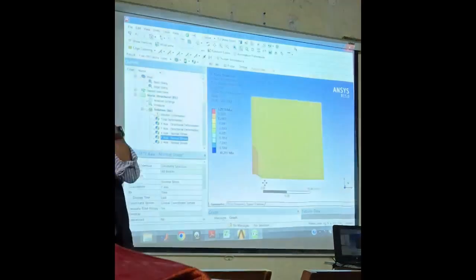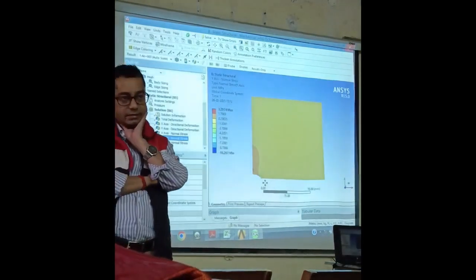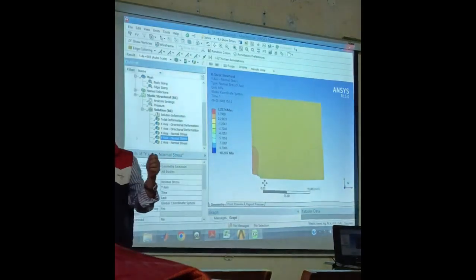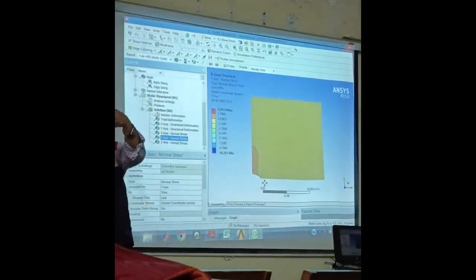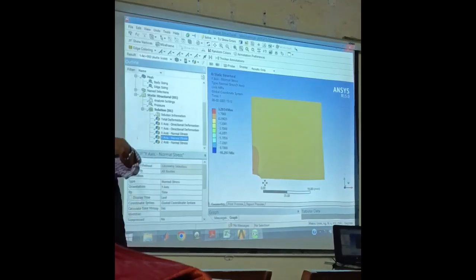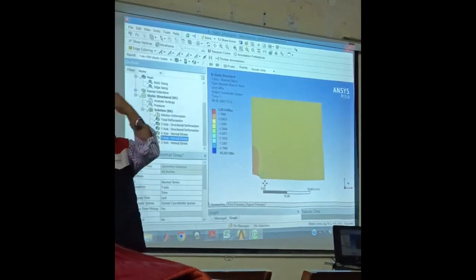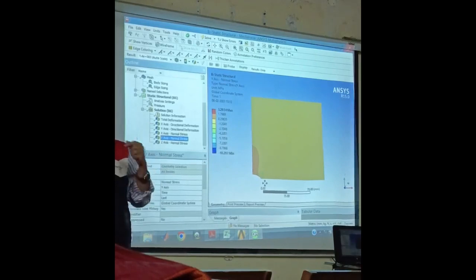You can recall, hoop stress was 2 times the axial. If it is so, say this is 100 kPa, sorry, 1 bar I should say. This is 1 bar, this is 2 bar, 2 times. So like 0.1 MPa and 0.2 MPa, roughly, in these directions.